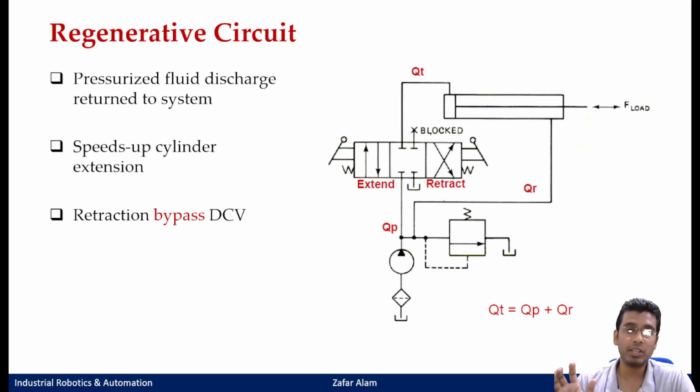When you apply your brakes, the energy from the brakes is regenerated, and that energy is used to charge your batteries. Because whenever you are applying the brake, that entire energy is wasted. So what you do is harvest that energy, and using a regenerative circuit, you use it to charge your batteries, so that when you are accelerating, you can use the battery power along with the internal combustion engine to drive your vehicles. So that is known as your regenerative braking system.